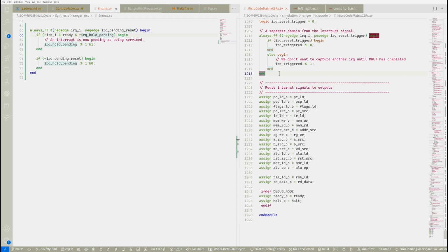So in the end, I went back to the control matrix, and I also renamed the signals because I didn't like the way they sounded to begin with. It's still a 1-bit FIFO, but it no longer is dependent on two separate different signals, as you see over here on the left. It's a single signal, a reset signal. And that corrected this particular error. This actually synthesized correctly. It took me a while to figure this out, but eventually, with a bit of Googling, I was able to see what the problem was. And so I reduced it down to a single signal.